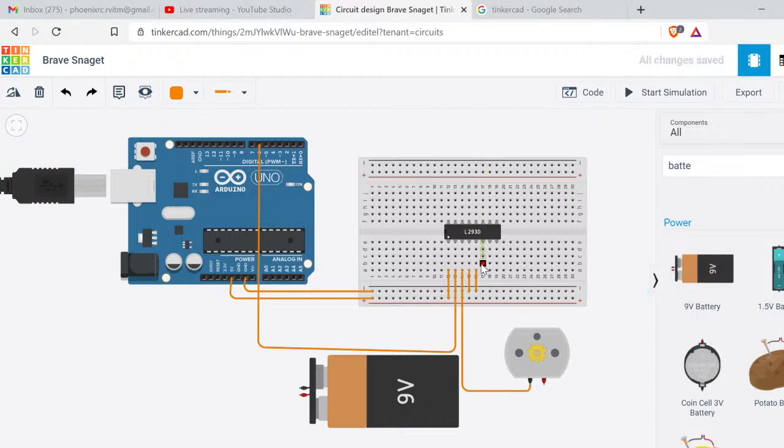And another thing, we have output 2. What is output 2? Because the motor has two outputs, we have to connect two terminals. One terminal is already connected and this is the other terminal, and this is input, because the motor can rotate in both clockwise and anti-clockwise.